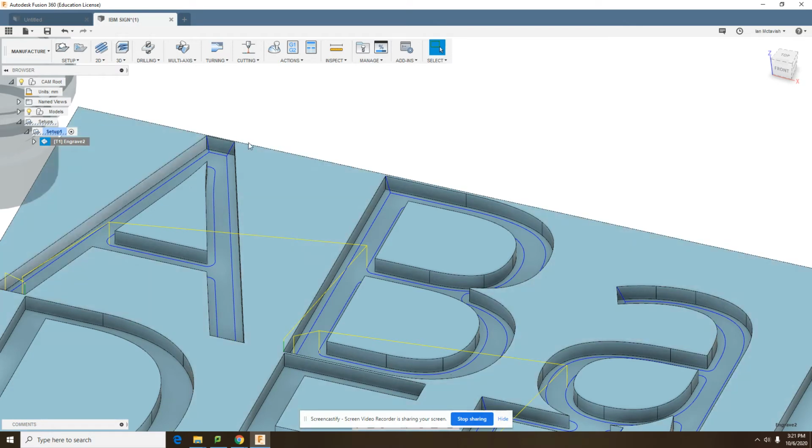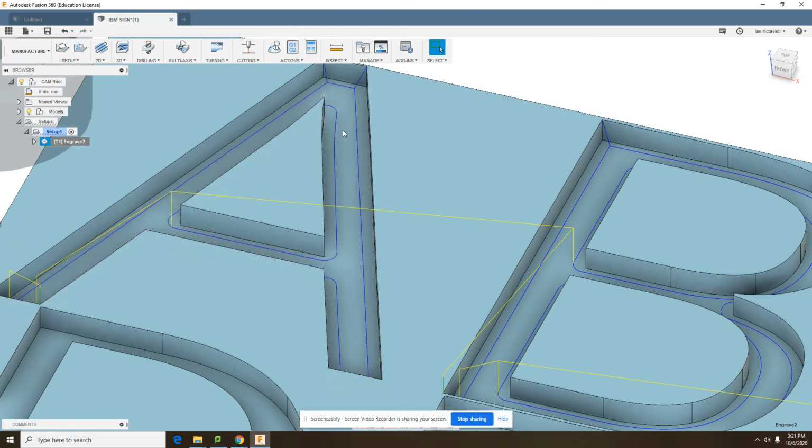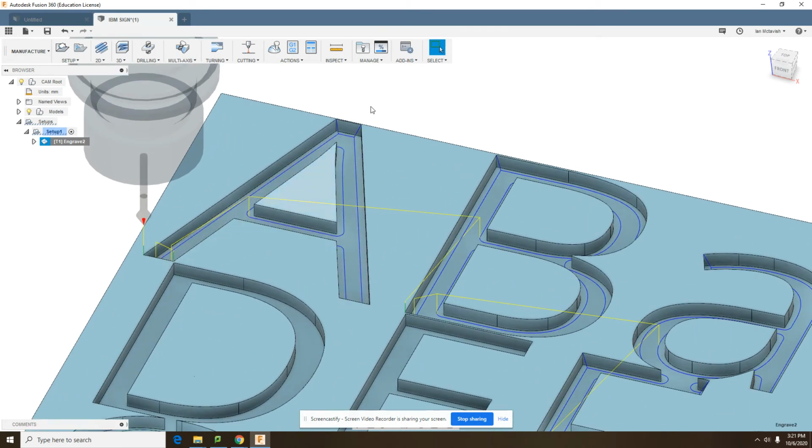Now, in here, you can see with my A, what it's doing is that it's engraving 2 lines in here. This is because this letter A, I believe it's about 4.5 inches thick. So it's a really big letter, much too big for this bit. So the bit can't do it in one pass. It does 2 passes. This will result in material in the middle. So the problem is I would need to use my 90-degree bit, which is bigger, and reset this. So pay attention to that.